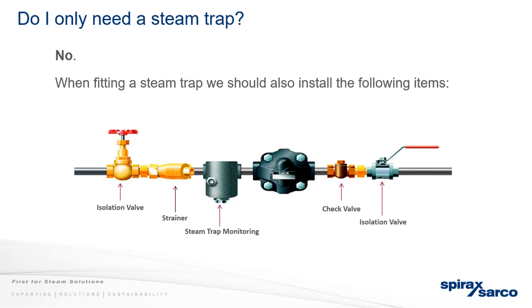Yeah, so the one other thing I will add with this drawing is the strainer is actually the wrong orientation on it. On a condensate line, you should have the strainer pointing downwards, not sideways. The strainer sideways would be for a steam line, and it's all to do with the fact that on a steam line, you wouldn't want a collection point of condensate that could increase the chances of water hammer. Whereas a steam trap is a full pipe of water anyway, or condensate, so you would have it facing downwards to capture the dirt. Yeah.